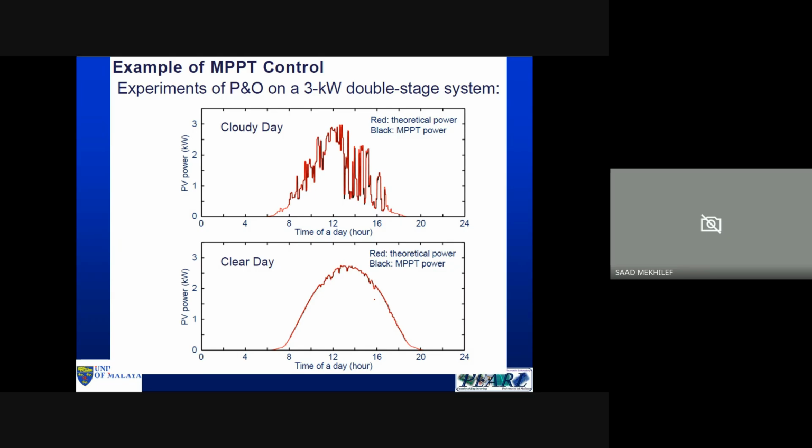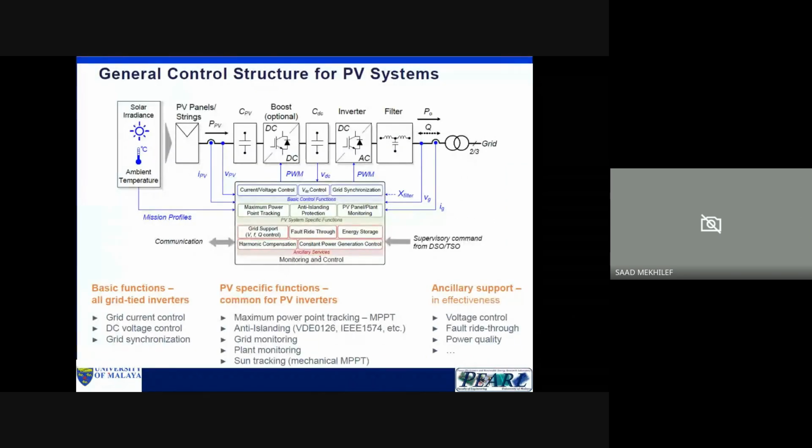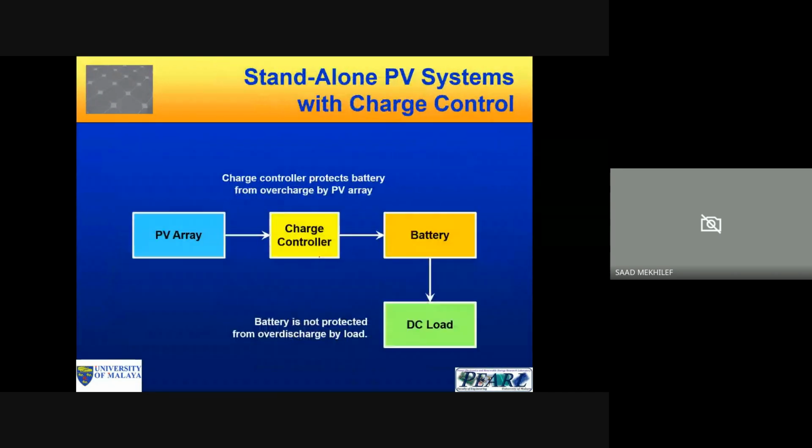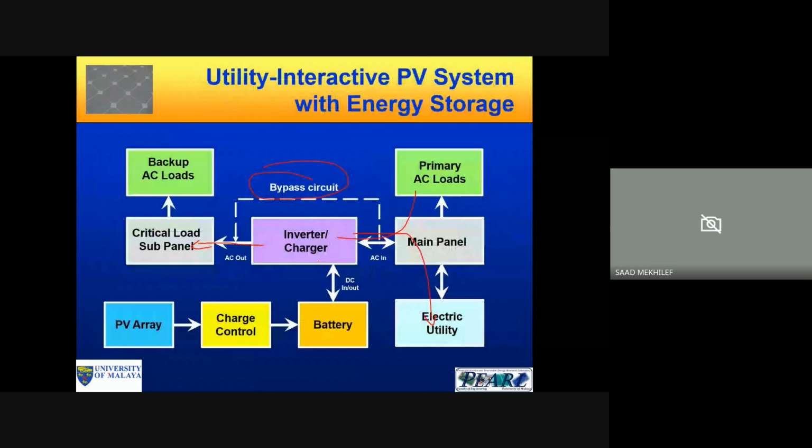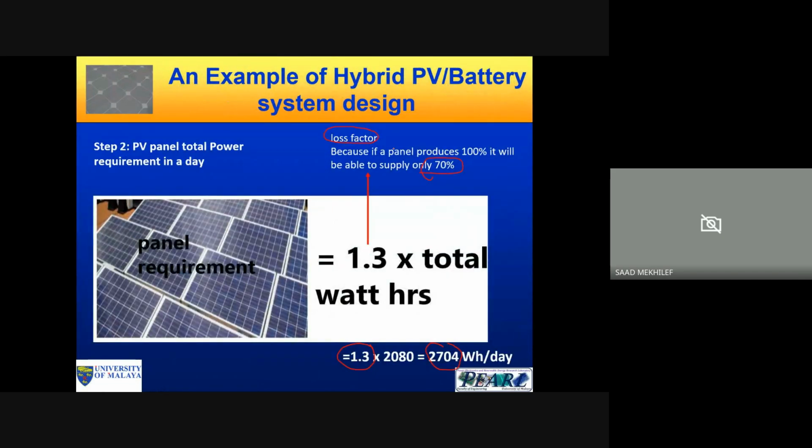Yeah, they are related to the sunlight, but it's different. The main difference is that sun hours means there is enough energy from the sun to produce power from the PV panels. Because if the power is too low, it will not be able to turn on the inverter or charge the battery. Yes, there is sun, but it's too low, so it's not sufficient. That's why we always use sun hours. We don't use sunlight.